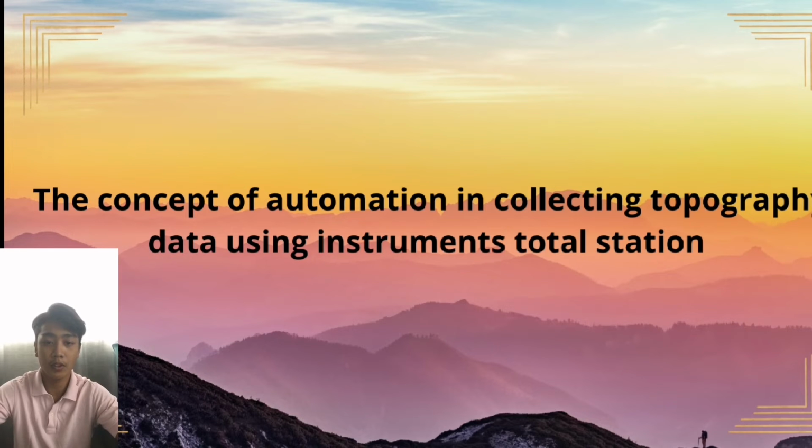The concept of automation in collecting topography data using instrument total station. First of all, for the data download procedure, all measurement data recorded from the total station may be transferred to a laptop or computer through cable, USB, memory card, and so on. Second, civil design and survey software can be used to handle data that has already been downloaded.